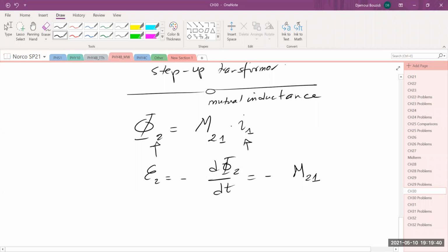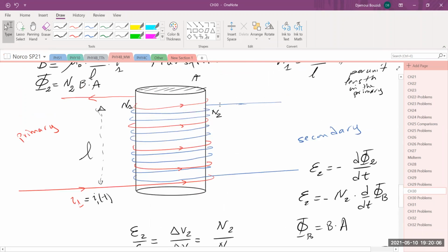Wireless chargers use inductance, by the way. If you put your device without plugging it in, the current is changing in the primary circuit, and there is actually a corresponding circuit on the other side, the flux of the magnetic field is changing, which induces a current in the secondary, and that is how you charge your computer wirelessly, or your phone, or whatever you're doing wirelessly. So this is the mutual inductance, and it happens without any contact. There is no contact between the blue wires and the red wires. There is only the flux of the magnetic field changing in one because of the current changing, that causes the secondary to actually have current in it, okay?